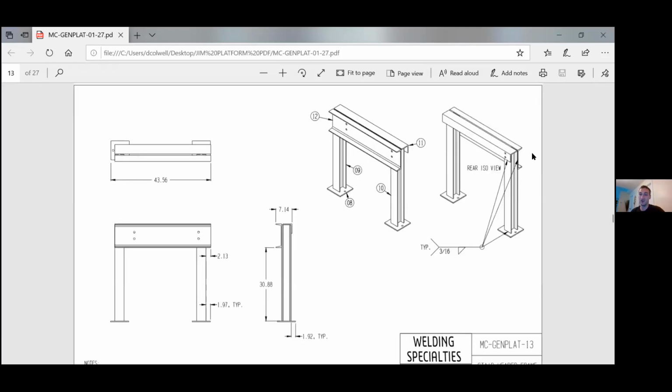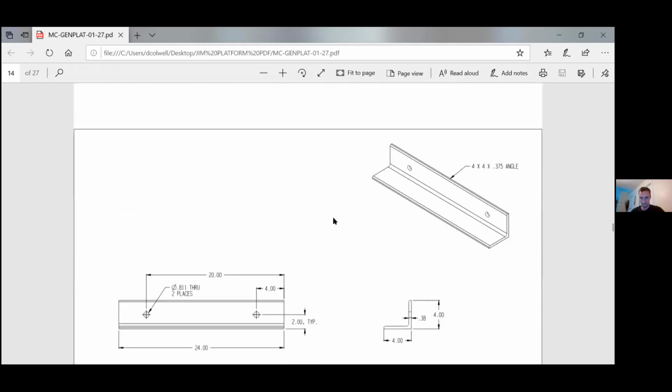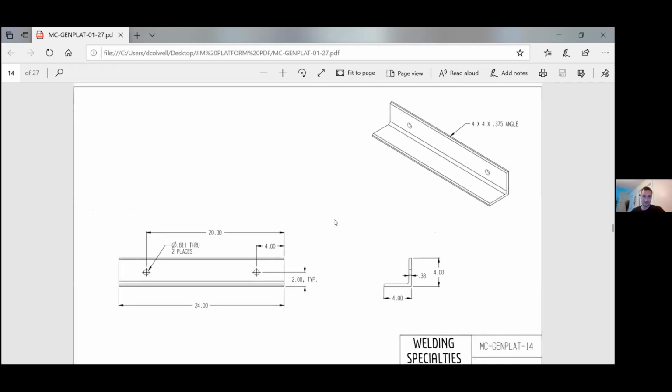If there's an area where you don't want weld because it's going to interfere with a mating part, weld seams basically add a radius everywhere they're put in, or a chamfer. Then you can point to it separately and say no weld here. And then it would say typical unless noted, or something. Just don't leave it up to guesswork. If you're going to do things that are a little unusual to save yourself time, note it well and make a note. You can add notes all over if you want to. Just try to keep it from being cluttered.